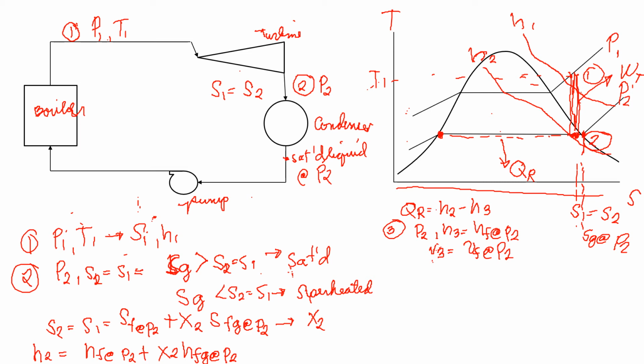The work of the pump is almost the same as isentropic, but we will assume this, and it is very evident that the liquid is incompressible, so we have a constant volume. So we have an isovolumic process.